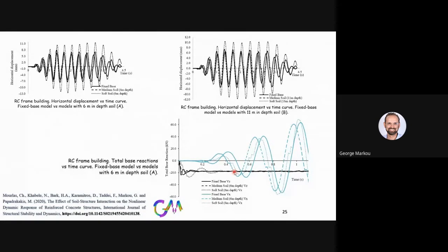As you can see here with the black line, the vertical oscillation is initially high at the beginning of the nonlinear dynamic analysis, and then it stabilizes, and therefore this shows that the actual vertical deformation and vertical oscillation does not affect the overall mechanical response, and we did not take into consideration a vertical acceleration.